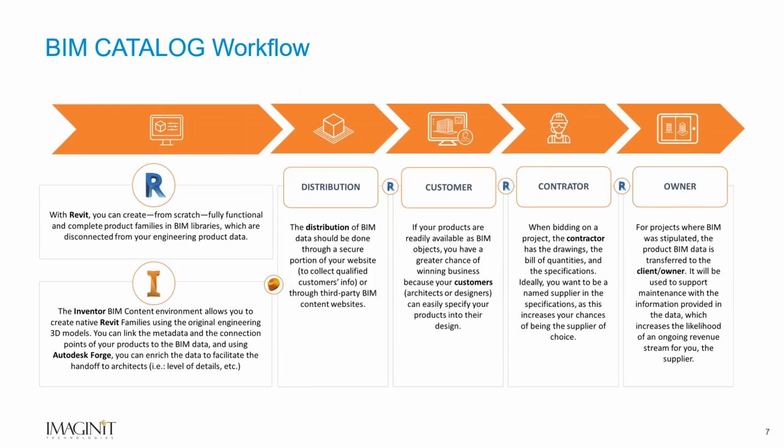Once it's a Revit family, Brian on his end can bring that in and use it on his side. So Brian, can you talk a little bit about families and where this catalog workflow fits in with that? Yeah, absolutely. Families are absolutely amazing when we can get that information from a manufacturer. The Inventor process of generating families generates what I call a static family. Think of a family as a block in AutoCAD. It's a static representation that's 3D with a lot of information potentially behind it.